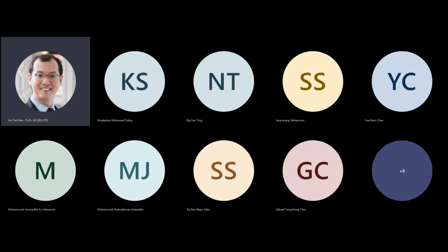So this is an artificial way of increasing, in a controlled manner, the number of free electrons in the silicon. We dope impurities, we insert impurities as a trick to increase the number of free electrons, because we're disrupting the lattice structure. We're intentionally using a material with a different number of electrons, so things are not balanced, and the excess electrons flow out and become free electrons, and they do not require temperature to escape the bonds. So our devices are designed on this idea that we add impurities to control the number of electrons.